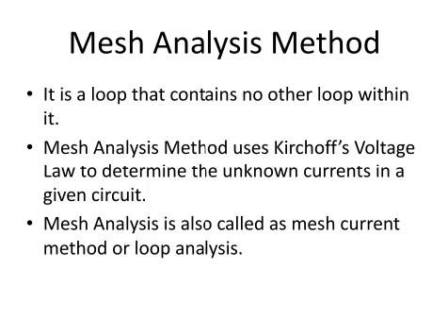The definition of the mesh is: it is a loop that contains no other loop within it. Mesh analysis method uses Kirchhoff's voltage law to determine the unknown currents in the given network. Mesh analysis is also called the mesh current method or loop analysis method.